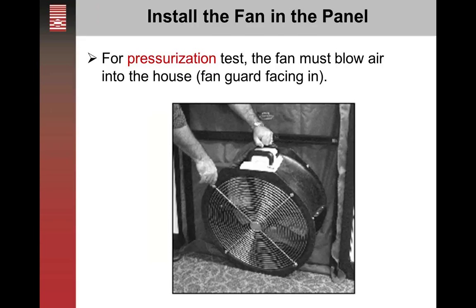The simple answer is there really isn't much of a difference. You will get a very similar answer. When you are depressurizing the house, many of the natural gravity dampers of the house, such as bathroom vents and the like, and range hoods, will help suck those dampers closed.